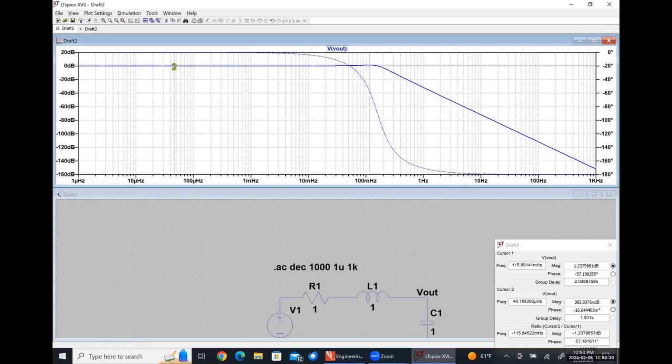So over here, right, where we're at effectively 0 dB, up here is our peak of around 1.25 dB. So whatever 1.25 minus 3 is, which seems to be like negative 1.75, that's our minus 3 dB cutoff frequency because it's measured from the maximum value, right?